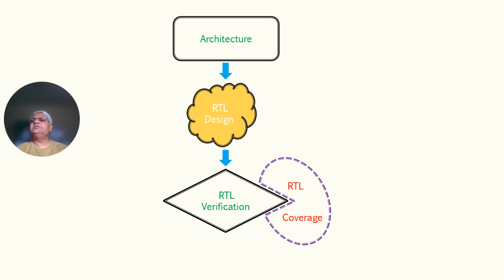So we compare what is expected as part of the specifications when so and so inputs are given, with what is actually obtained when the same input vectors are excited to the RTL design. If there is any discrepancy, then the RTL design will be checked. Okay, so this is how static verification and dynamic verification are performed.